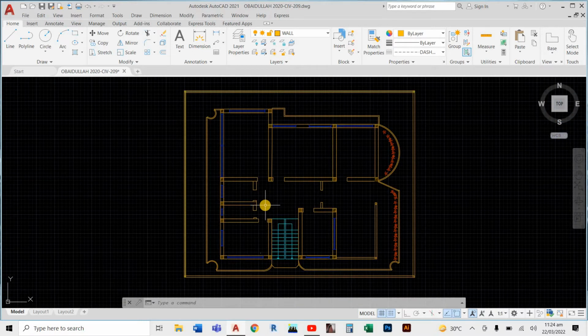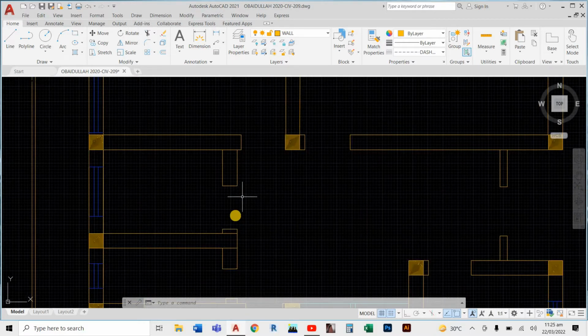After deleting, now we are going to talk about the dimensions of the lintel. First of all, the thickness of the lintel should be between 2 or 3 inch. The width and the length of the lintel should be the same as your opening length and width. For example, how much is this length?